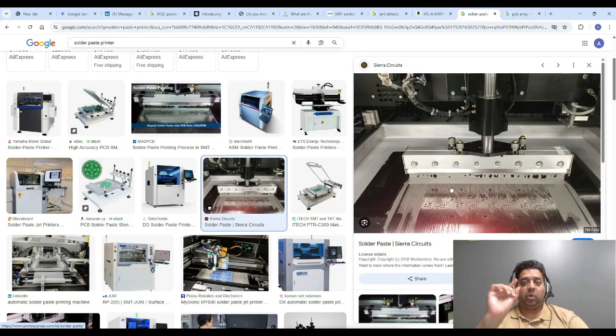So if you miss one pad, your stencil is going to be wrong. So that's why engineering has to make sure all the pads are there and the sizes of the pads are correct as well. I don't want to go too much into how to determine the correct size, because that's really going into the engineering side, outside the scope of this video, but you can figure all that out later.